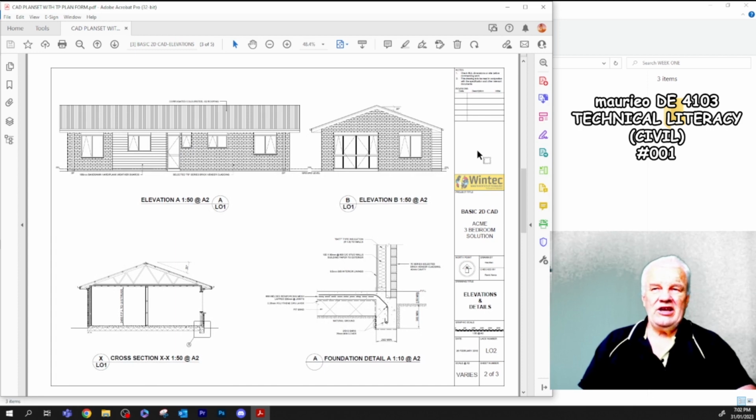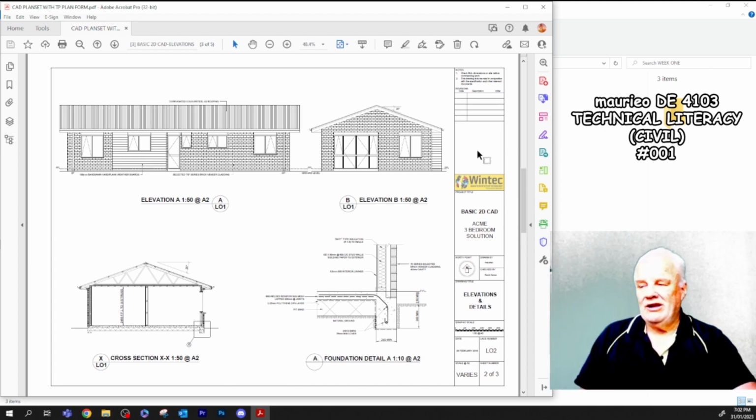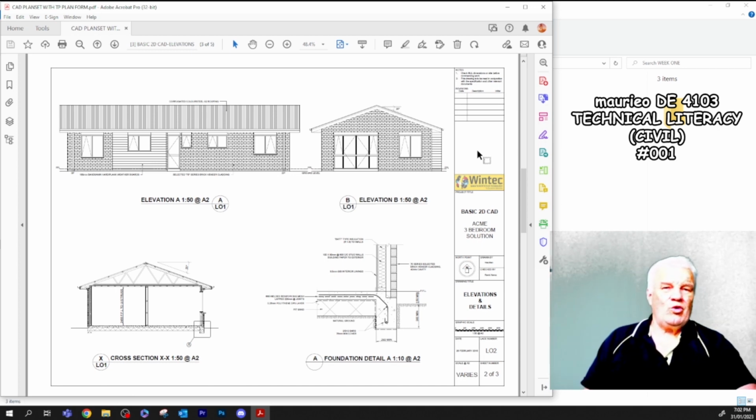And then this here is some elevations. Again, we draw the elevations in civil and structural drawing, but the cross sections are what we call X-refed in, which is CAD speak for cut and paste. Well, one of the key things of drawing, any drawing, but in particular CAD drawing, is you only want to draw something once.